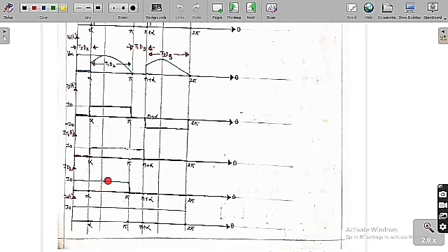So now I want to draw the current in the diode. Let me assume I want to find the current in the diode D2. As you can see clearly, D2 is going to conduct from 0 to pi. So 0 to pi, D2 is conducting, and in the remaining regions, D2 is not conducting, which means it's open circuit. So the current through the diode D2 is 0 in this range, whereas in this range, the current through the diode is equal to the load current. So it is also equal to I naught.